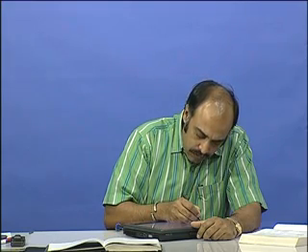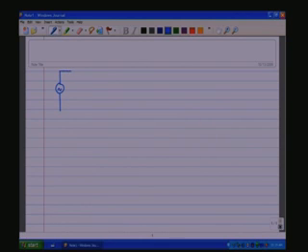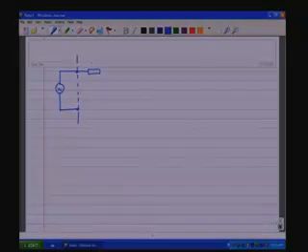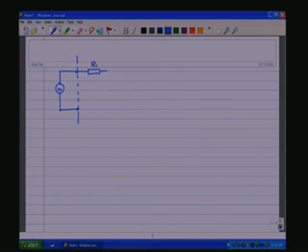So, starting from the equivalent circuit of the transformer, which we have evolved in the last class, we have a source E g, and this is where the terminals of the practical transformer begin. There is first a resistance R 1, which represents the winding resistance of the primary coil, and then you have a reactance, the leakage reactance due to the leakage flux.